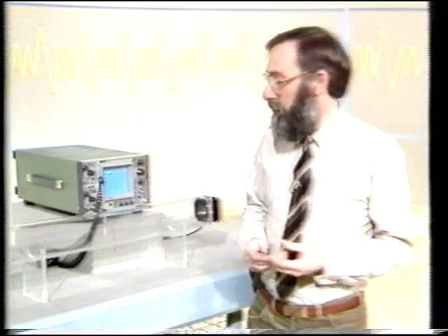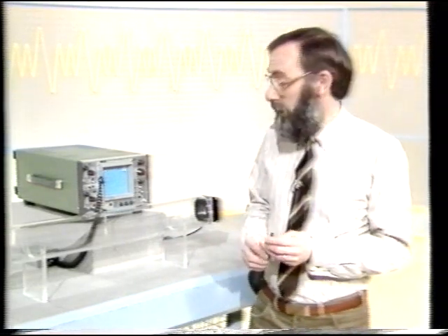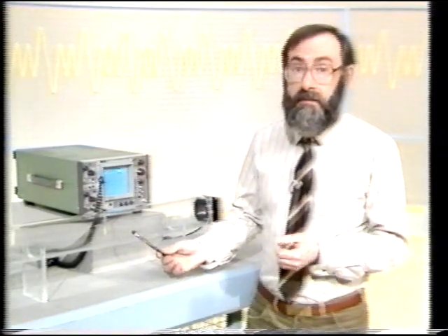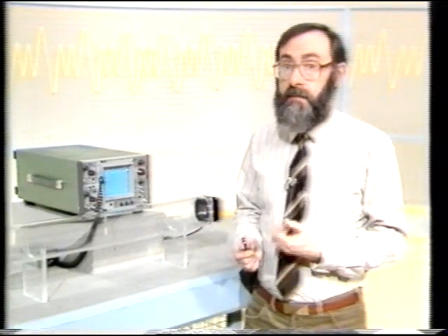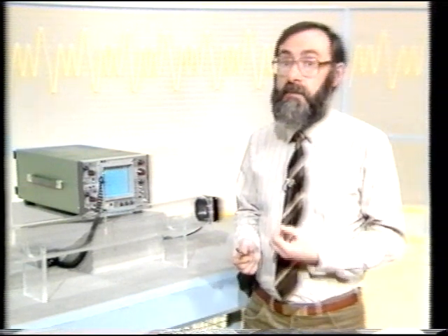In case you're wondering, the probe I'm using is a hot wire anemometer. The essential part is a heated element here. It's open to the air, and it's held at a constant temperature by an electric current flowing through it. The moving air has a cooling effect. The faster the air, the more heat it takes away from the element. And the current required to hold the element at its fixed temperature is used as a measure of airflow.